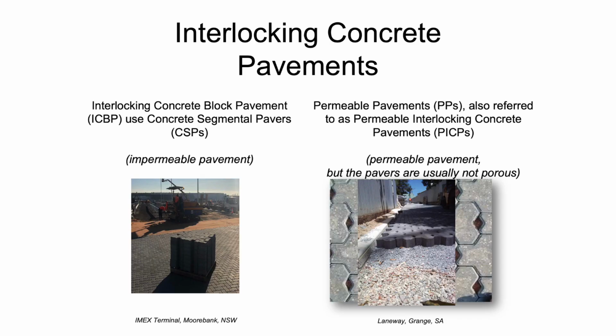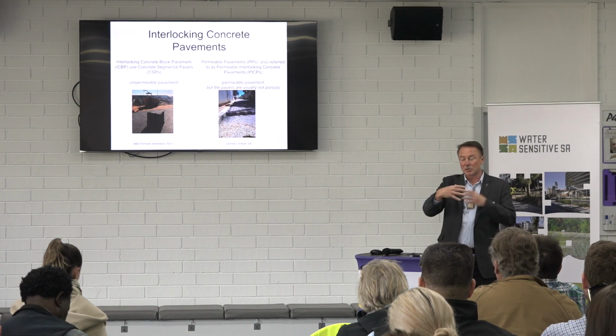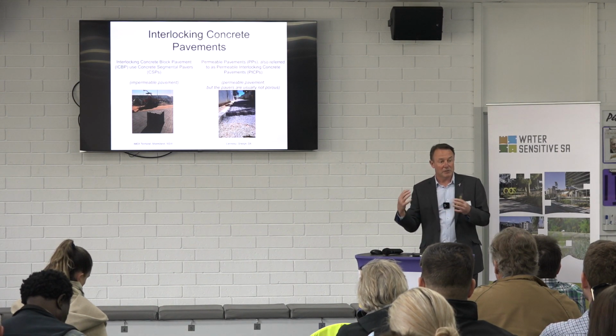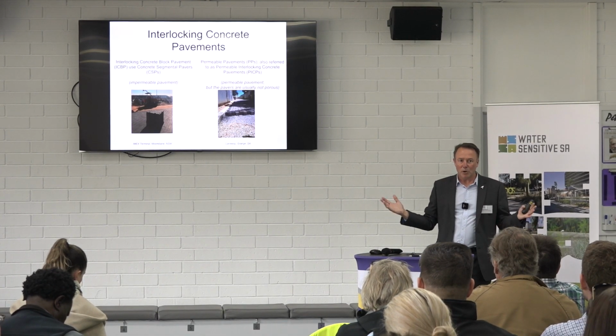Whether you're dealing with permeable pavers or interlocking concrete block pavers that are impermeable, they both do the same thing, and Arlene did touch on this, they lock. They're designed to lock. And they lock through some horizontal forces that happen through rotation and wedging, fundamentally. That all falls over, doesn't work, if you don't have good edge constraints in. The whole point of the locking and the rotation, working together to lock, is that they displace each other very, very slightly at the beginning, and they try and push the pavers out.